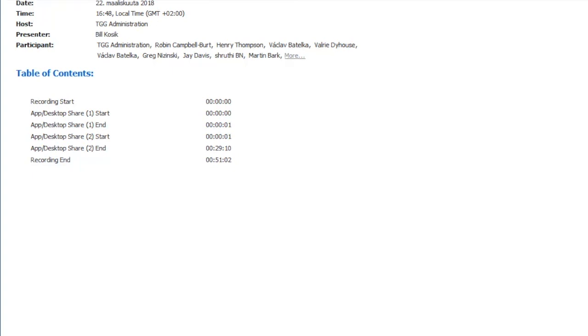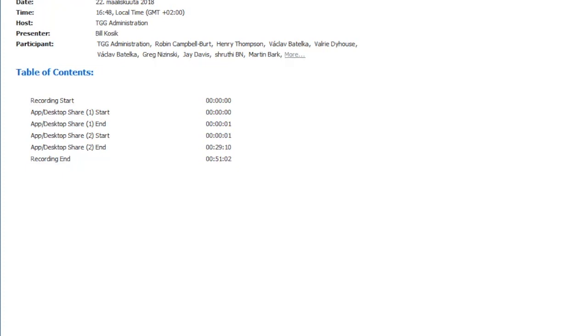No, it doesn't right now, but that is a fantastic idea, because especially as we're going to much higher water temperatures, there's definitely a reuse for preheating, boiler makeup preheat, and such. You sent me some ideas: heating pools, floor heating, industrial. So absolutely, as this becomes much more of a norm, and I truly believe it will, and the temperatures become much warmer because of the energy considerations, we're going to have the ability to reuse a lot of that energy that's built into that water for other things. So it's great.